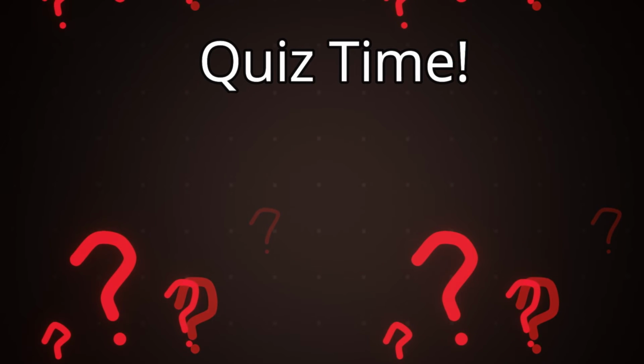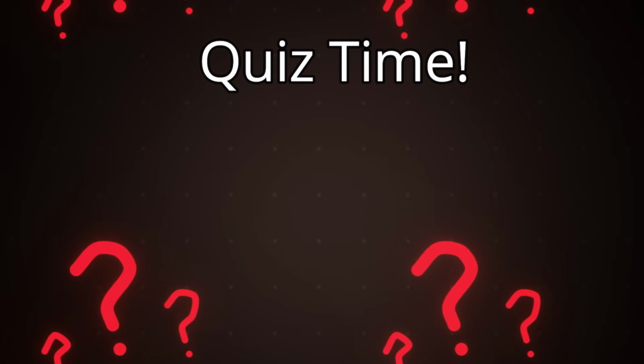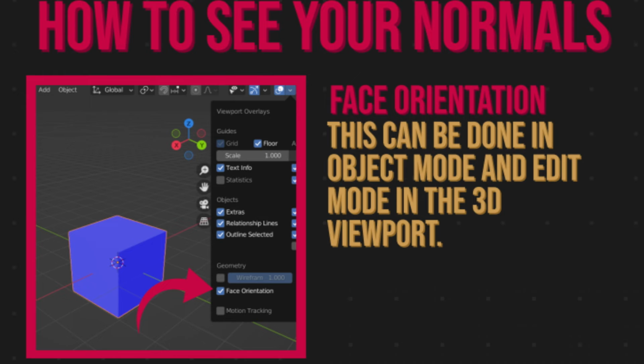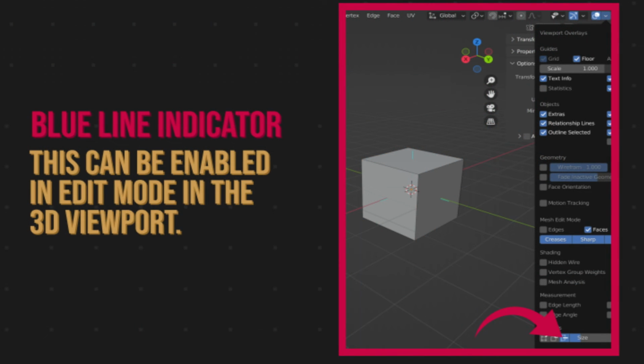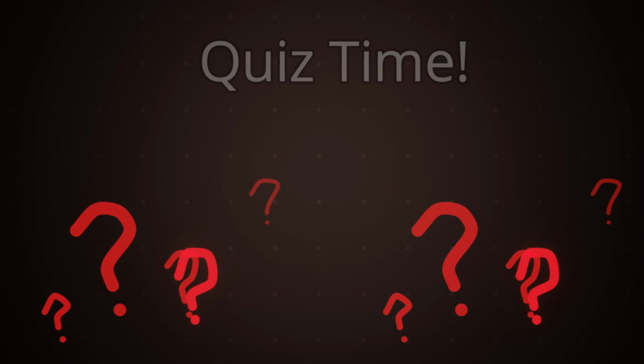Number 3, how can we visually see if our normals are facing the right way? The first way to do this is to enable the colored face orientation in this drop down here in either object or edit mode. The second way is just in edit mode, where we enable our normal direction blue line here, which will show us if our normals are facing outside or not. Since we need our normals to be facing the right way in order for our shading and certain modifiers to work properly.